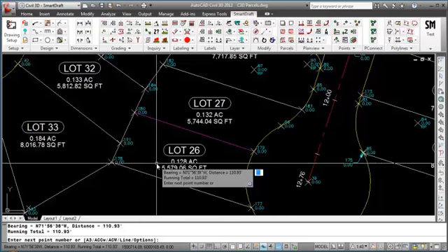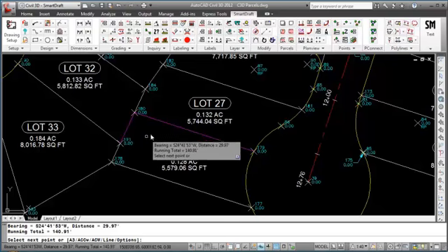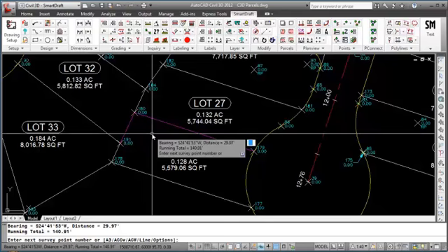I can change either by going into options or typing S back to the select mode and select 191. Since we do have a survey database, I can type D, and now I will get the point information from the survey database. I can type in 178 to get the next point number. Again, change to point number, not survey database, and type 177. We encounter a clockwise arc.